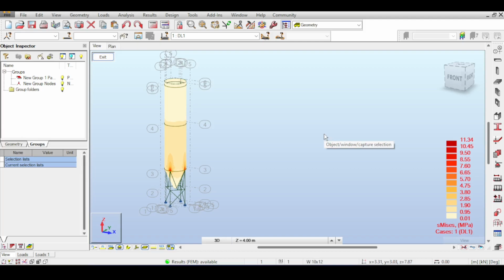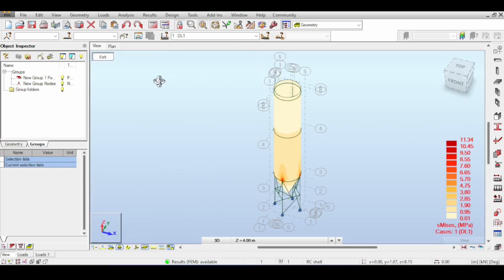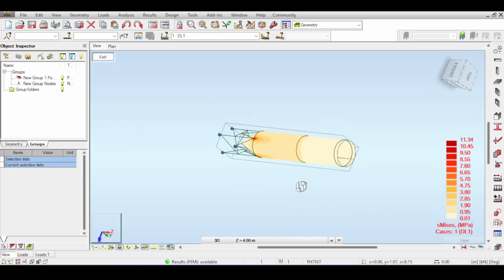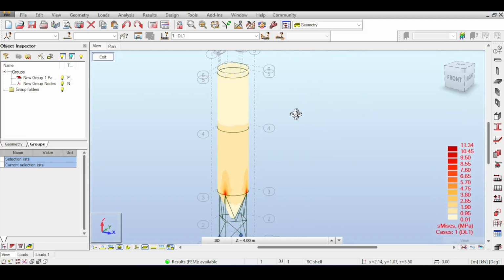I have not done this, but there is a full science of handling forces and how you can assume a crane load here pulling and a crane load here pulling, because you would be transporting this horizontally with a crane, the crane that lifts this silo up. So you would have to deal with this type of load, and you would have to design for this type of load, especially for structures that are being transported. Examples for structures that are being transported are precast concrete structures and silos and any functional structure that can be displaced.